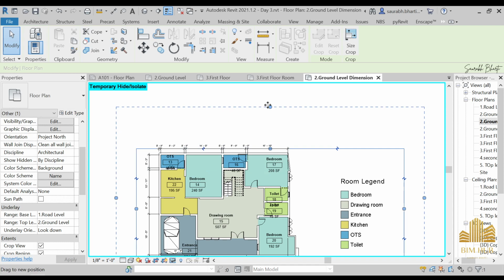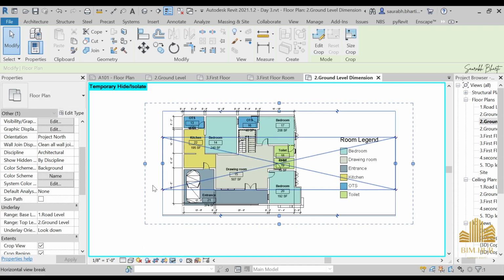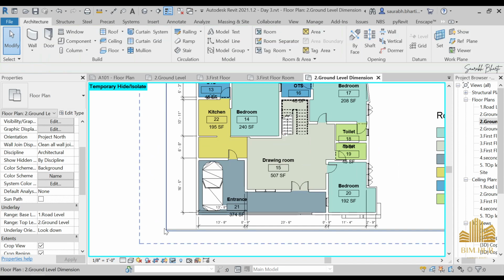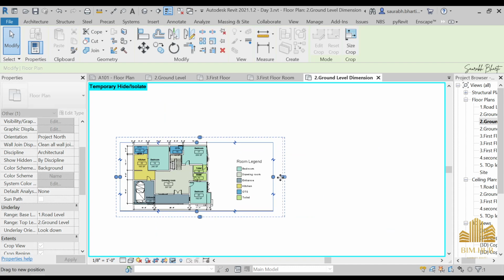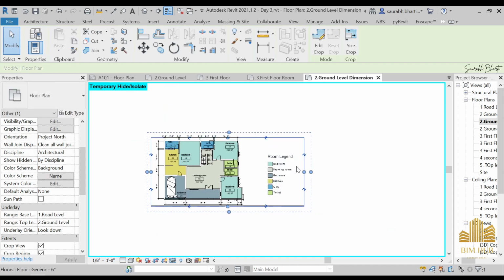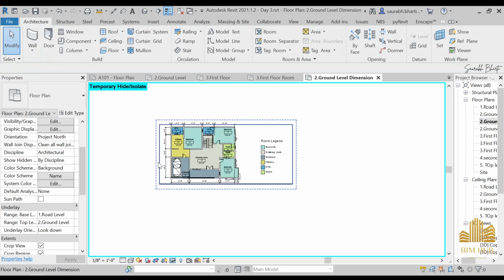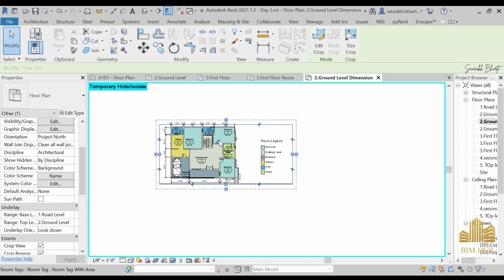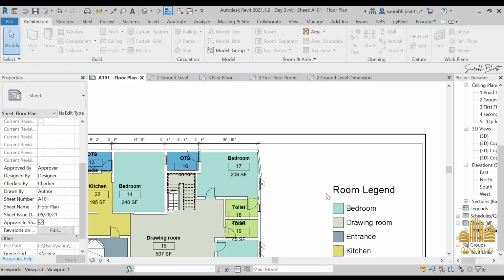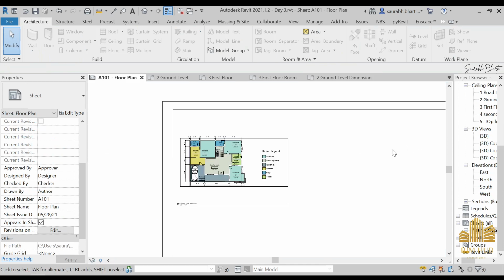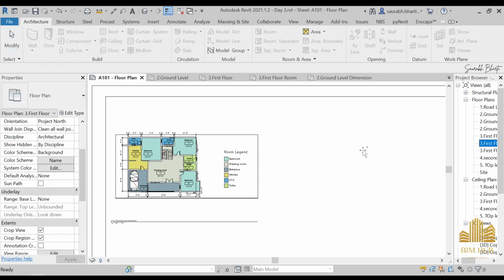Okay, so this is the annotation crop, and if you want to use it, you can use it, or by default also Revit provides a correct dimension, so you don't have to worry about that. So it is a little bit constrained, I mean it is partially constrained, not fully constrained, so you can also change the size of it. So now that we have provided the constraint view, I mean this floor plan of the first room, you can just do the same thing with the second one.